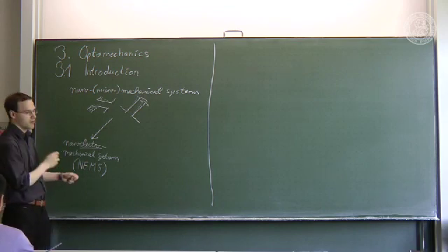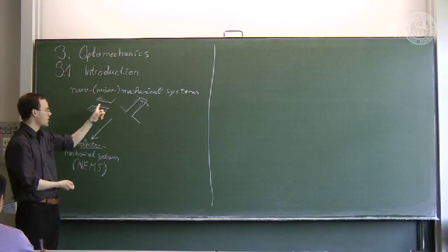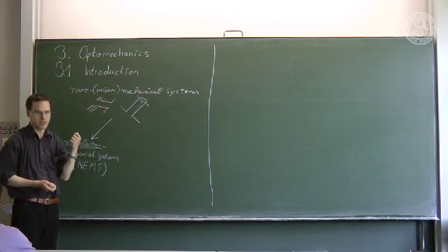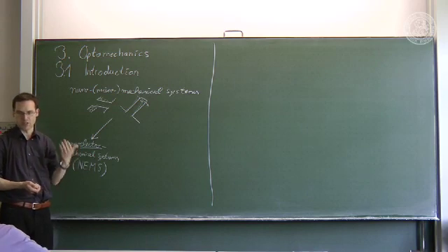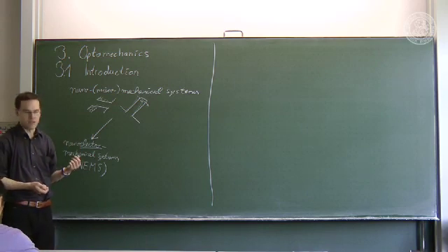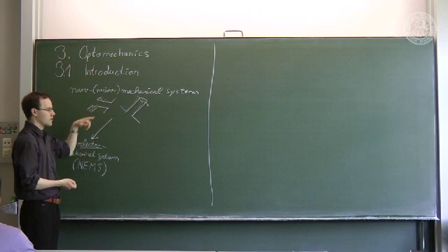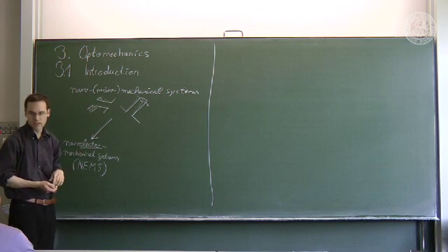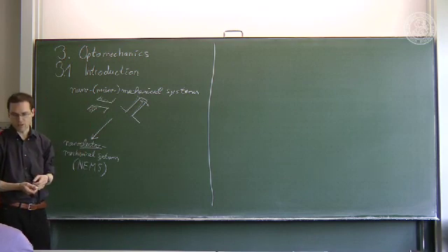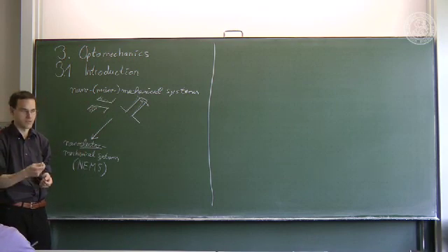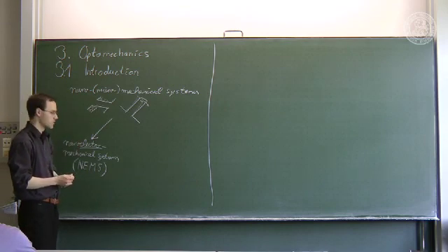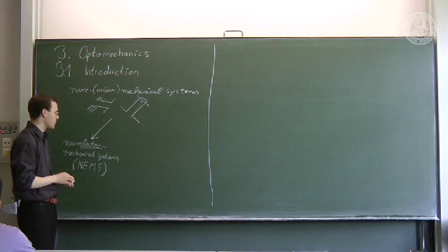It's not hard to imagine how that might work. For example, if you charge any of these beams and then you apply an electric field nearby and have a time-dependent electric field, then you can just drive the motion of this beam. In addition, if this beam then starts to vibrate, and for example it is part of an electrical circuit because it is metallic, then you might observe a change of its resistance or a change of the voltage applied to this beam, and so you could read out the motion. So that is one approach.